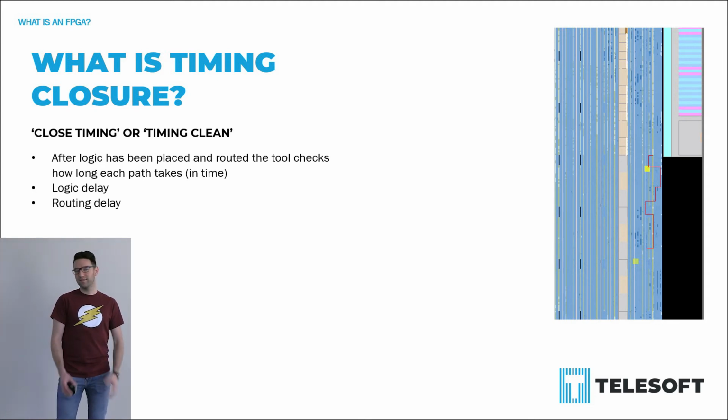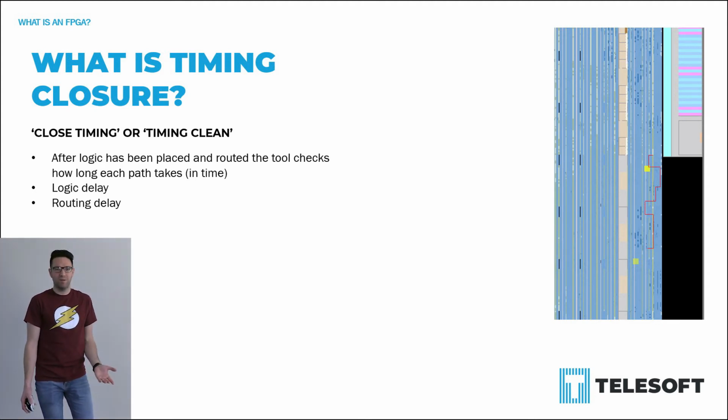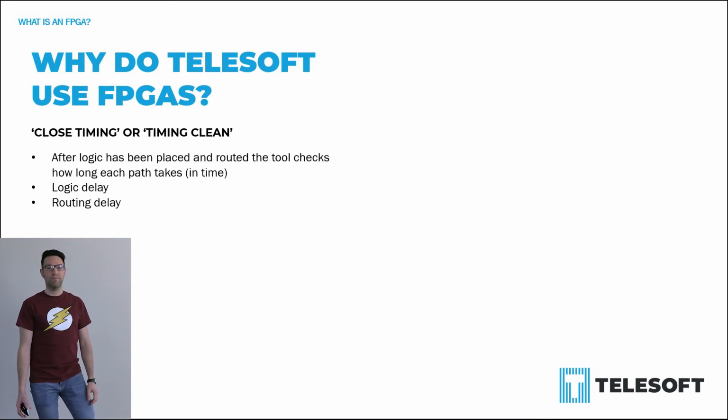So the next thing is, all of this sounds quite complicated. So why do people bother using FPGAs? What benefits do they bring to us? Well, the first thing, it offers massively parallel processing. So let's think about what this actually means. If you think of an FPGA running at 300 megahertz, but then you compare it to a processor running at 3 gigahertz, you'll often think, well, how is an FPGA any faster than a processor? The processor is 10 times faster. Now the difference is due to the parallel processing.